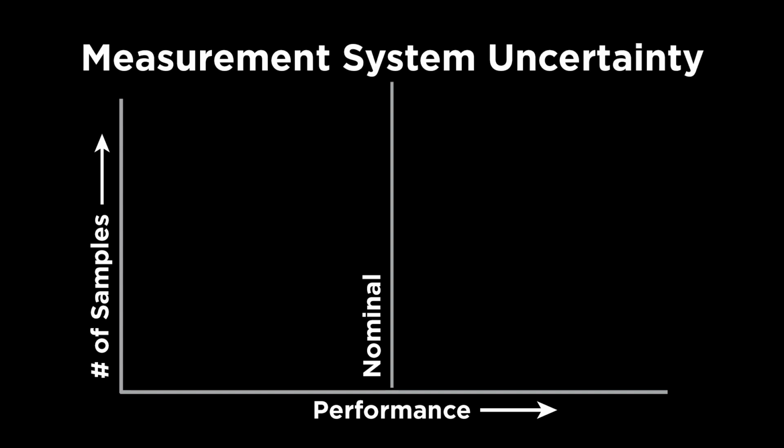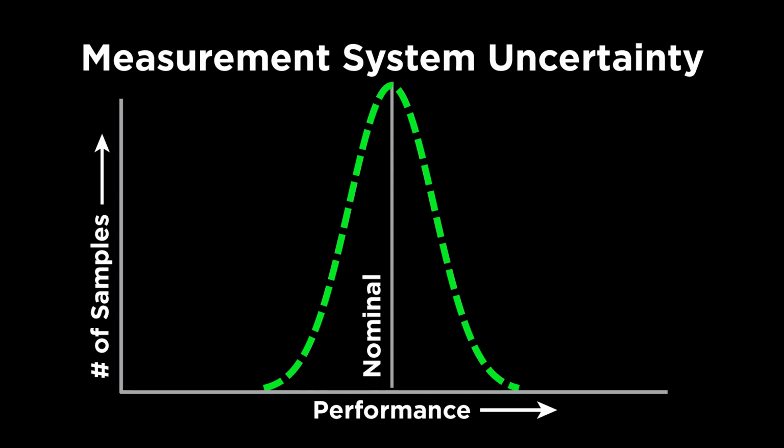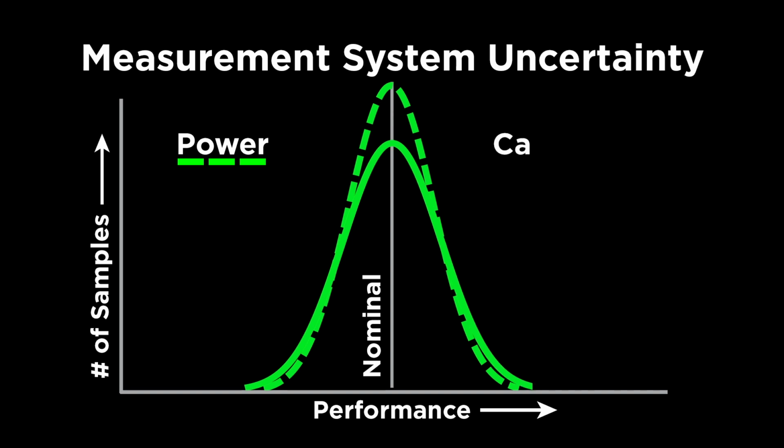First, measurement system uncertainty. Differences in instrumentation coupled with other factors such as refrigerant properties, oil circulation, test point deviation, and stability of operating conditions will have an effect on both the power consumed by the compressor as well as the capacity that it delivers. This measurement uncertainty can be as high as 1.3% in power and 2.1% in capacity.